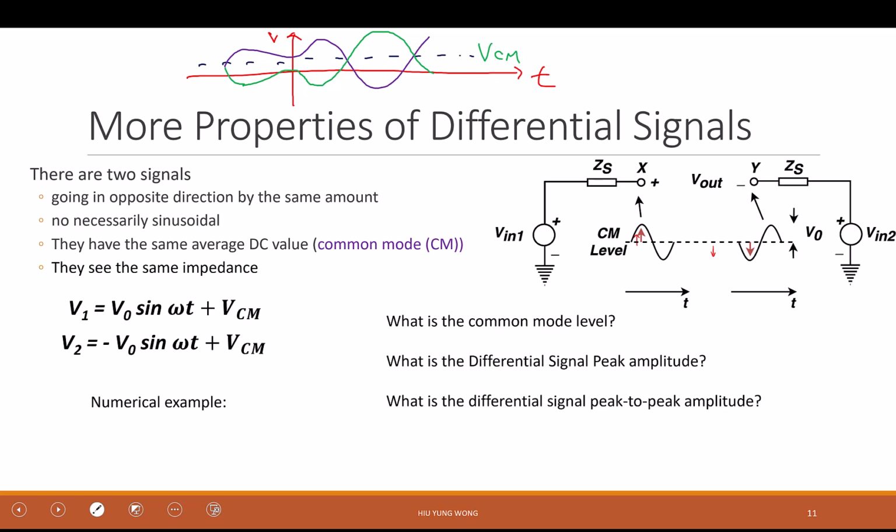If you have a lot of noise, you need to go at a lower frequency, because in principle, if you have a bit go long enough, when you do the averaging, the noise will be gone. Then you can resolve whether it is bit 0 or 1. Now, if you have differential, you get rid of the noise, then I can have a shorter bit width, right?